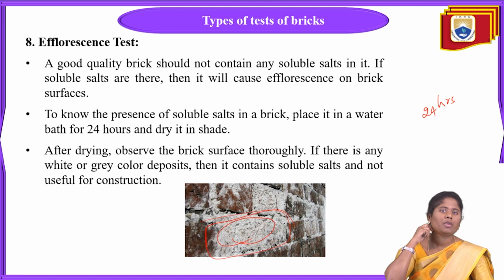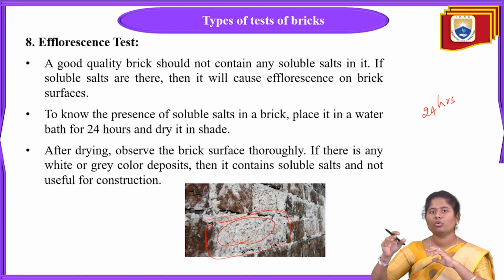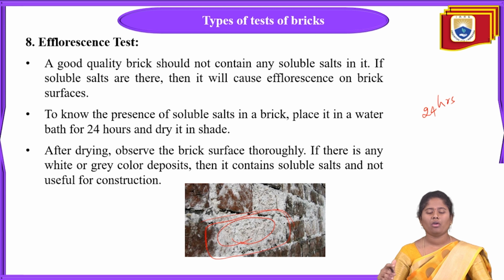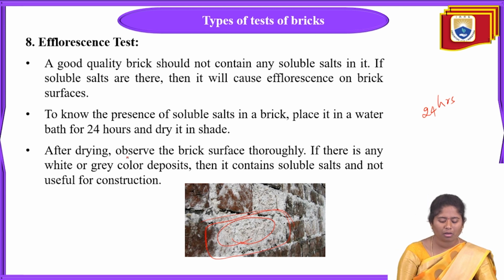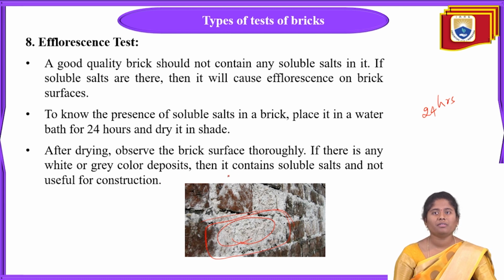After taking that brick from the water bath, we are going to expose that brick to the sun radiations. After that, we are going to observe the brick surface thoroughly. If there are any white or grey color deposits, then it contains soluble salts, and that brick cannot be useful for the construction process.